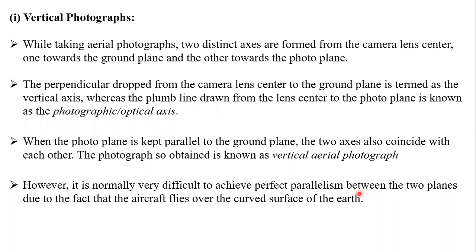So a perfect parallelism between the two planes is difficult, because the aircraft flies over a curved surface. You can't say the Earth is a flat body. Whenever you go to a very high altitude, the Earth will look curved. It won't be flat, what we see regularly as land. The Earth's surface is curved. So it is very difficult, students. We can't get a perfect vertical angle, and there will be some tilt in the angle. That is acceptable, no problem.